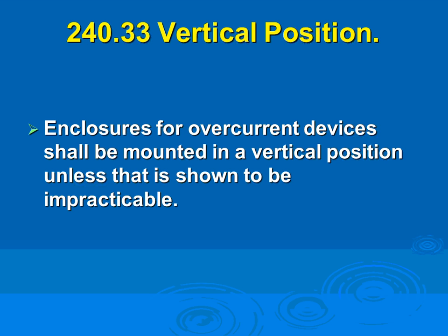How are you going to show impractical? That's kind of the word, yes? We have a situation where we're trying to change out the panel, and it's got a cinder block wall this high. The panel won't fit anymore. So instead of building a wall, we haven't addressed it yet. Here you go, impractical. Grab 240.33 and talk to the inspector. Say impractical.